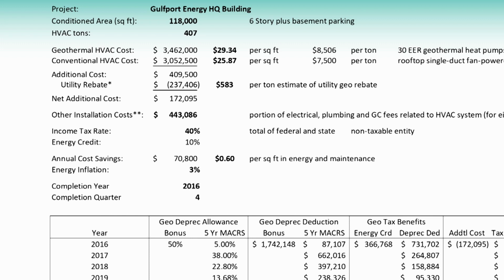All the buildings we're showing you are using cloud-based controls, where the thermostat is the smart device, and then they go to a portal that's an energy management portal. And you can see a lot of the same stuff you'd see in a DDC system on that portal. All your scheduling, anybody can do it. The owner can get a phone app and they can change things. So once we started promoting that, full-blown DDC went by the wayside for geothermal heat pump systems.